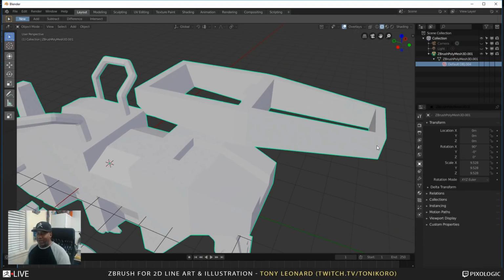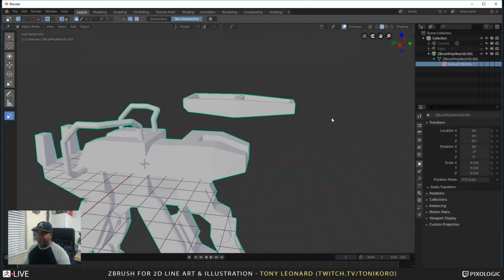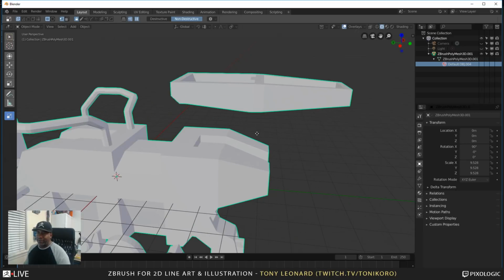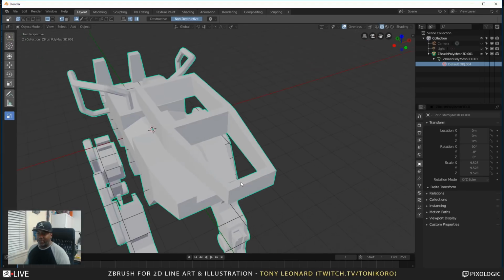But basically what I wanted to do in Blender is just show, as an example, where I take a lot of this stuff. So I'm going to hit Alt-W on the keyboard, which activates the Box Cutter element of things. And as you can see here at the top, I can either work in a destructive or non-destructive manner.